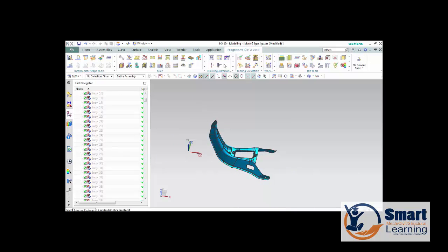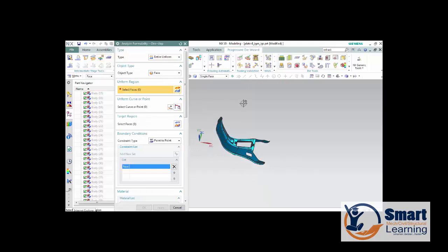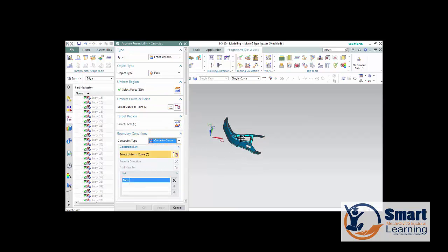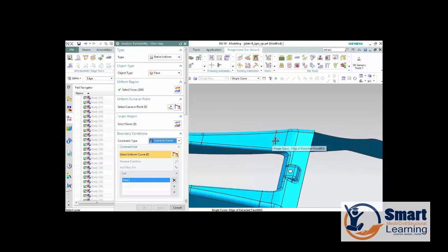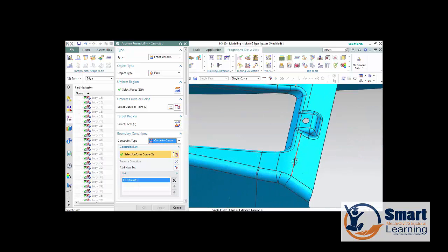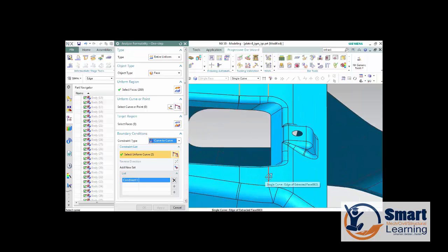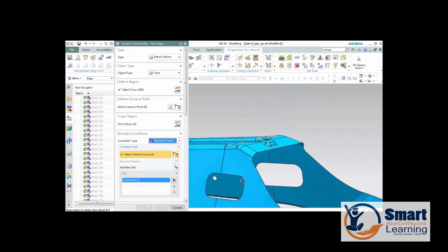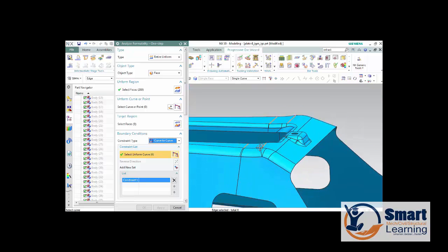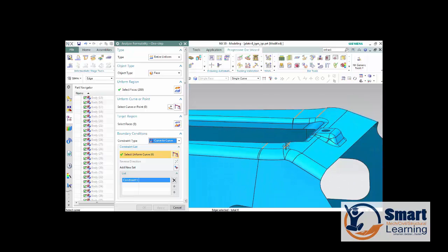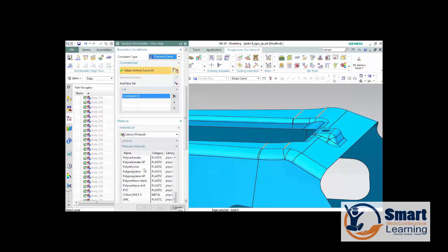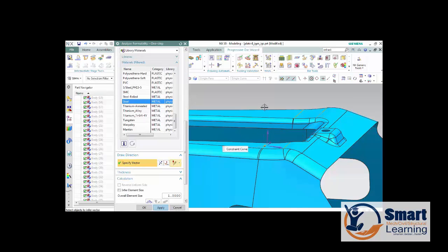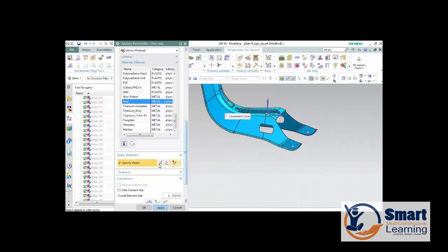If you go to progressive die and one step forming, go to entire unform and select this, and here I'll go to curve and select some flat areas. I think actually this is a curve area. I'm just assuming this as a flat area, and I'm selecting my material here, specifying the vector. You can see the vector direction.